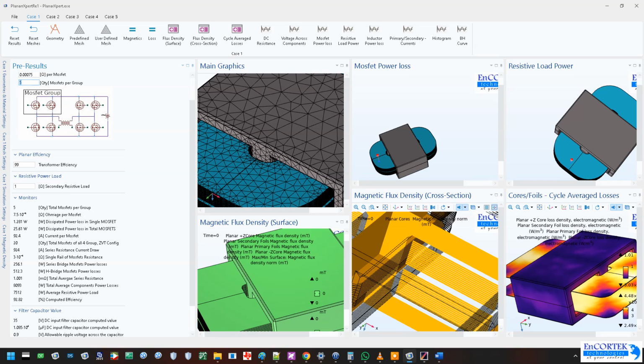Say 6, we'd be at 24 MOSFETs, efficiency going up there. If we use 10, well, be careful with capacitance, efficiency going up to 95. So let us just use 5 MOSFETs, we are at least over 90%, which is fine, right? So you have decisions to make over here, so I will have to put these in these boxes over here to help make that decision, right?